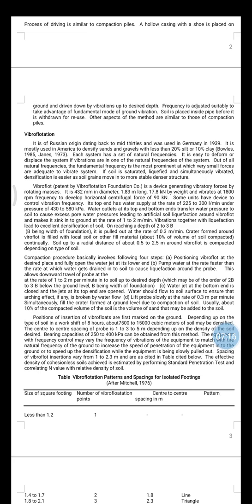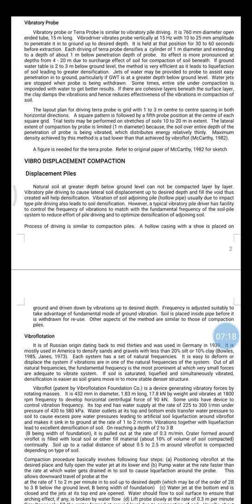Have you understood? So the next method is called displacement piles. Displacement piles are also a process like compaction piles. In compaction piles, we insert a pile and we densify the surrounding soil. Same thing in displacement piles also.